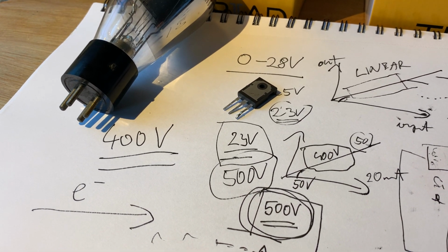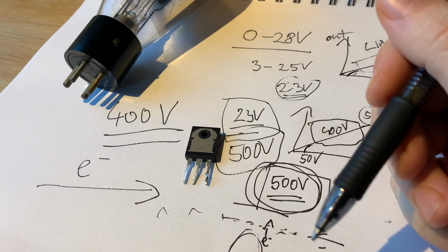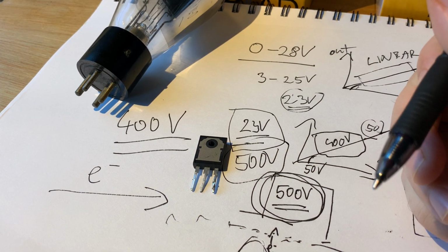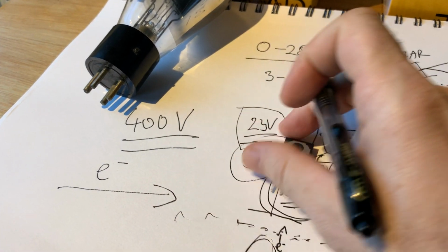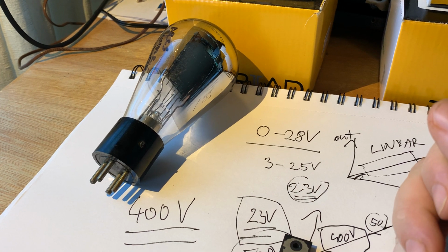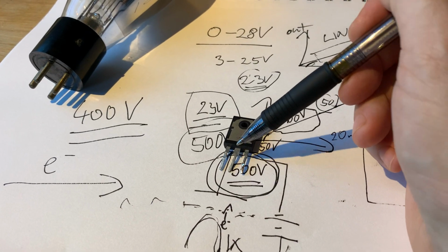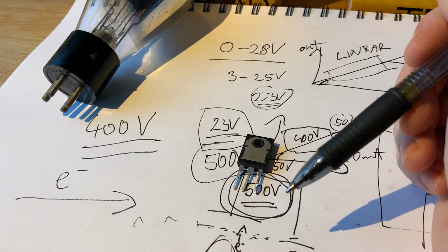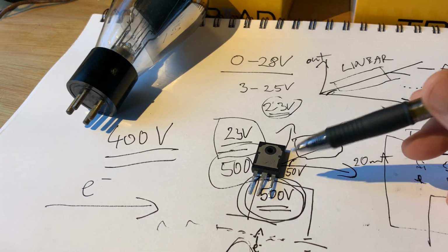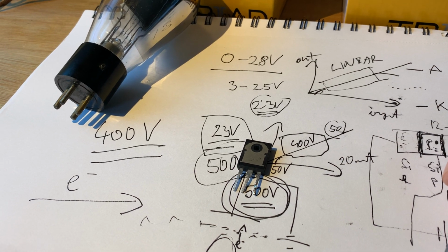As a consequence, what people do with transistors is they employ a lot of feedback loops to correct their behavior. However, that causes lots of problems. For vacuum tubes, you do not need to employ that many feedback loops. If you want, you can use vacuum tubes without any feedback whatsoever. With transistors, it's extremely hard to do. There are very few people using low feedback transistor designs, but it's not something that can be done on thousands of amplifiers. It's really something truly specialized.